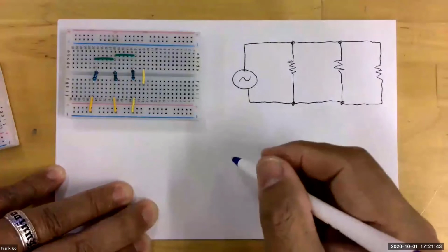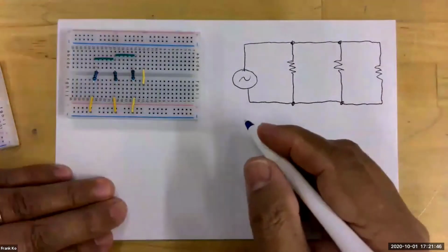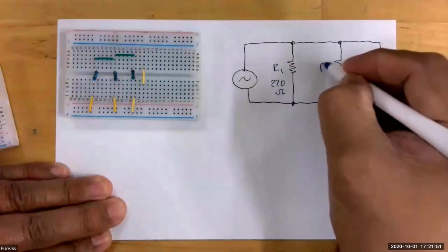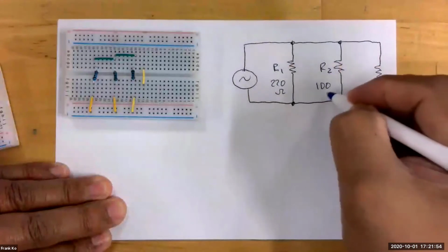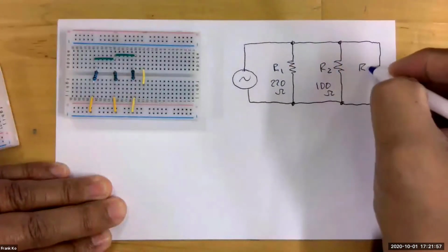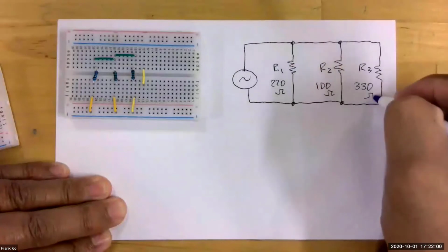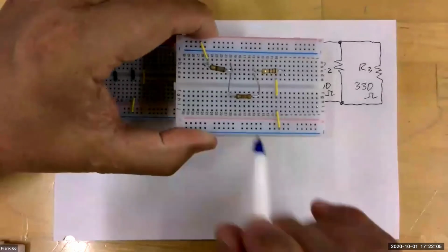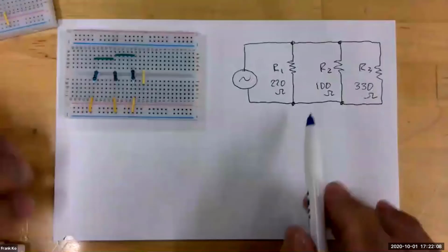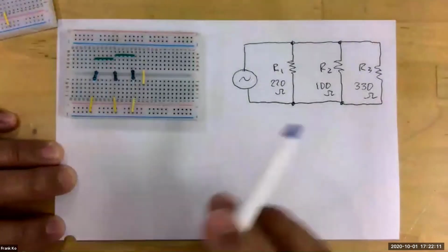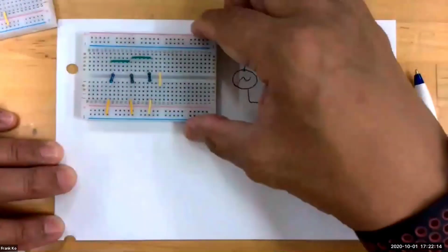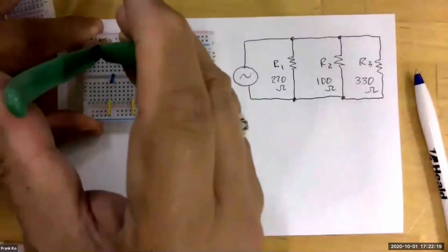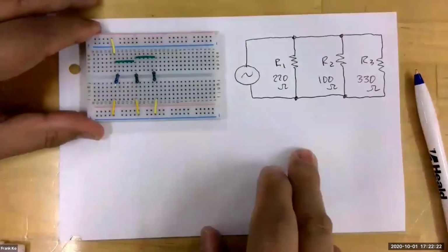And you have these resistors as well, and I'm going to ask you to do your R1 as 220 ohms, your R2 as 100 ohms, and your R3 as 330 ohms. So you have these resistors, the first set in the large ones that I've given you, and the second set can be the small ones that I've given you or that are part of your kit. And so when you go to build this, it'll look very similar to this guy right here that we built before. I'm going to connect this guy up here, and there would be your parallel circuit.